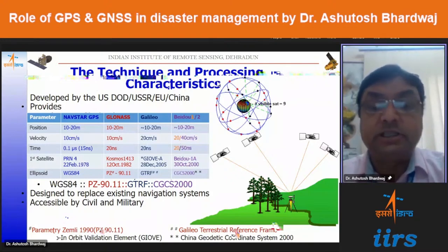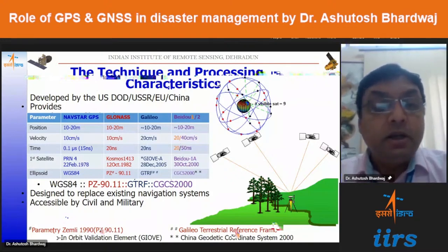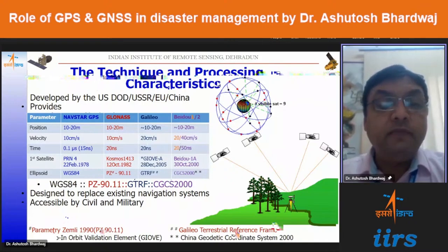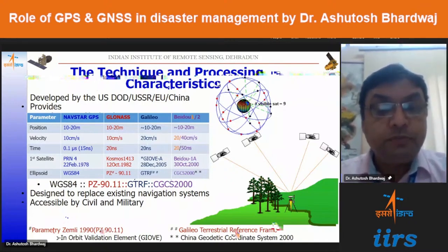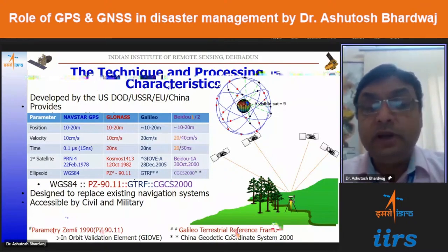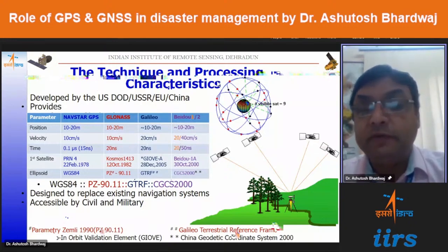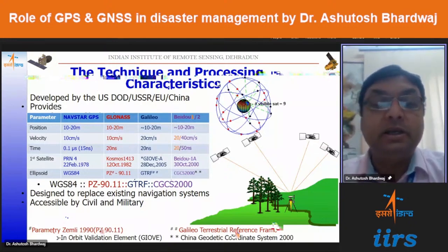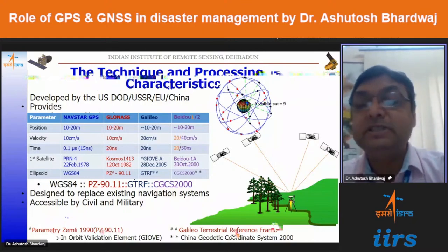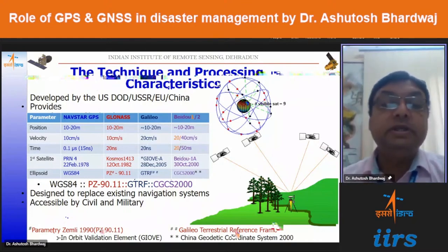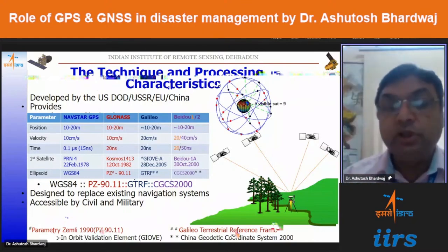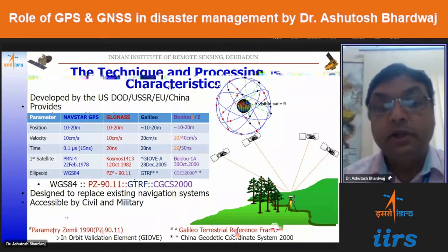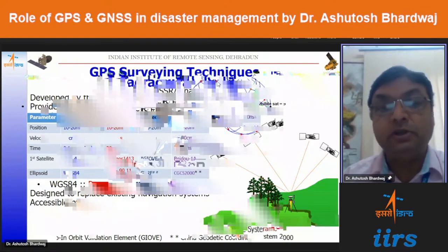specific post-processing system, wherein we process and survey with particular SOPs. And when we are talking about centimeter and millimeter level of accuracy, that is basically derived from the phase-based solutions. The code-based solutions can provide us a solution at the level of meters only. So primarily what we are doing nowadays is the use of the phase-based solution.